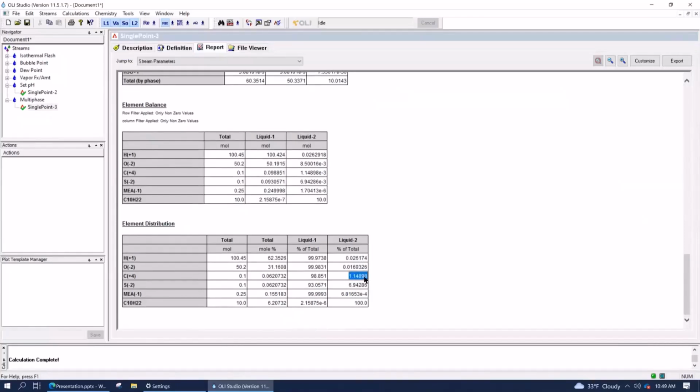If you remember right, we had between 80 and 85% of the CO2 and H2S in the hydrocarbon phase. Now with the excess of MEA, that's essentially been removed. Since CO2 is more reactive than H2S, it's more acidic than H2S, it's not surprising that the CO2 was neutralized to a greater degree than the H2S. And also just to let you know, there's a certain solubility of MEA in the oil phase, not entrained per se. This is thermodynamically essentially stable in it.